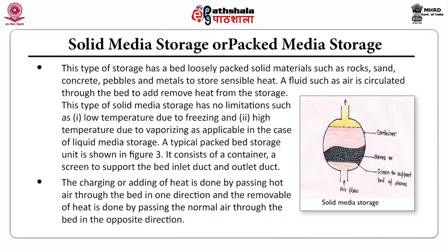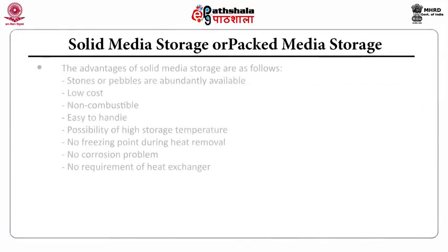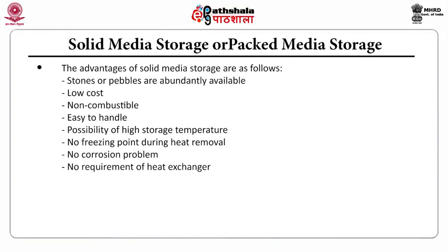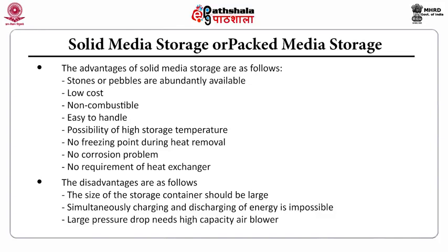A typical packed bed storage unit is shown in this figure. It consists of a container, a screen to support the bed, inlet duct and the outlet duct. The advantages of this solid media storage are: the stones or pebbles are abundantly available, low cost, non-combustible, easy to handle, the possibility of high storage temperature, no freezing point during the heat removal, no corrosion problem, no requirement of a heat exchanger. But it has disadvantages like the size of the storage container is large, simultaneous charging and discharging of energy is impossible in this media, and large pressure drop needs a high capacity air blower.